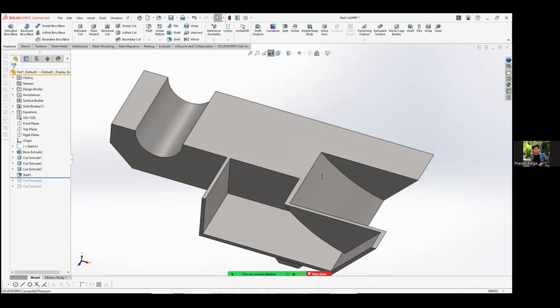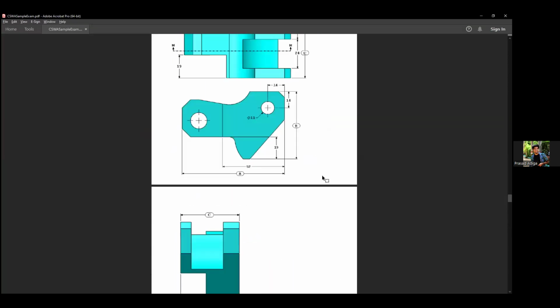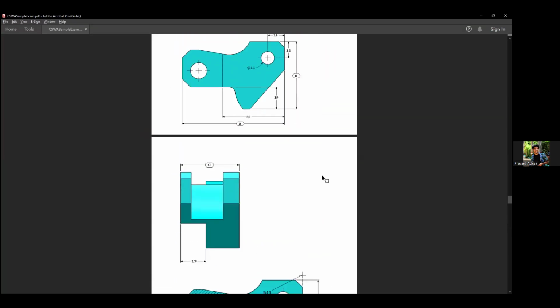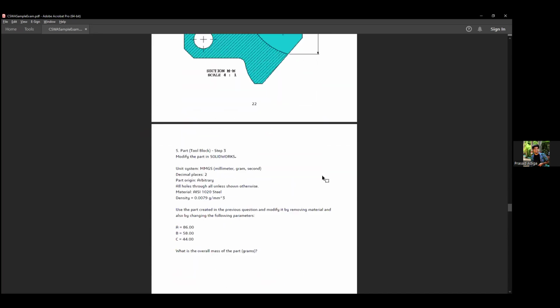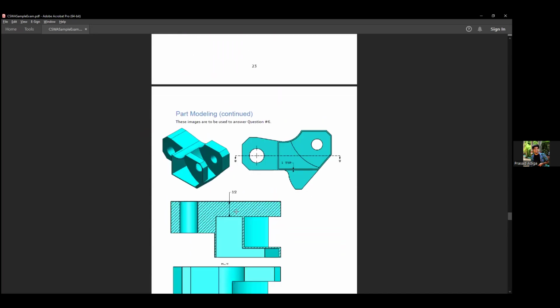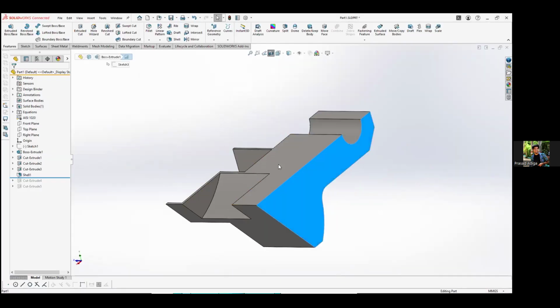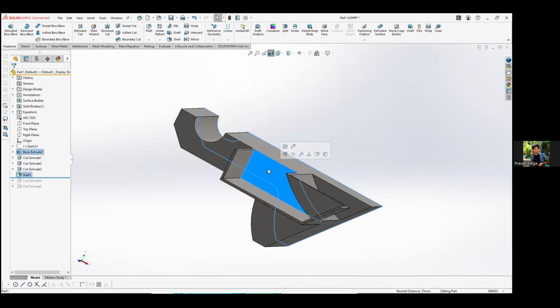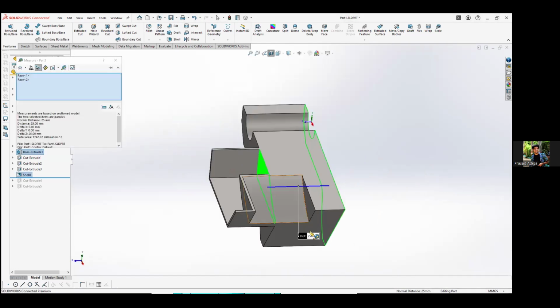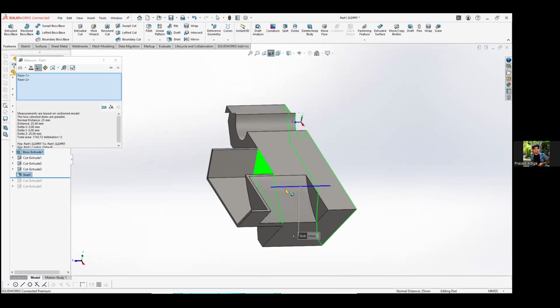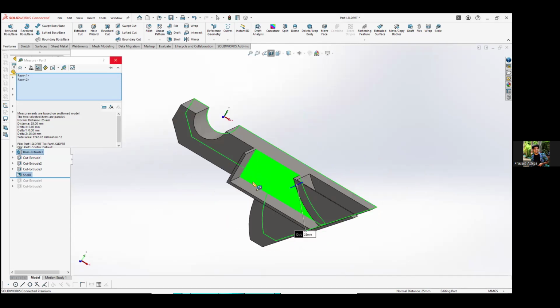So in the exam, in the question, what they have given is the shell has to be at a distance of 12 mm from the back side, right? But in this way, the distance between this and this is not 12 mm, it's more than 12 mm. It's 25. So you need to create one more thickness, cut extrude command to remove the additional 13 mm.